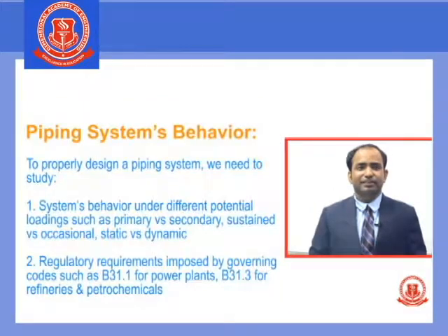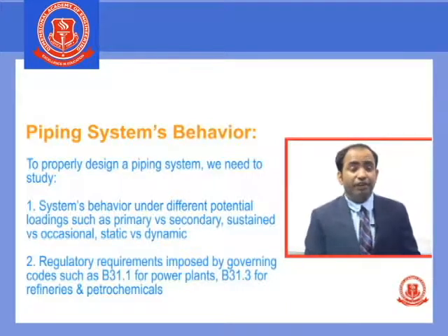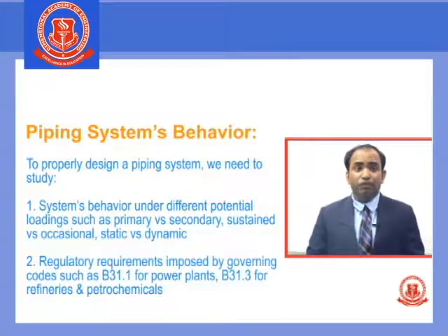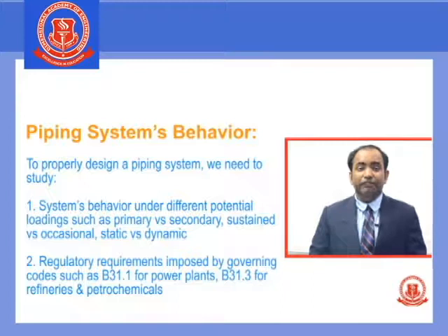To understand the piping system, we need to understand the behavior of the piping system. We need to do the behavior study under different potential loading conditions, such as primary versus secondary, sustained versus occasional, static versus dynamic. Under all the different possible potential loadings, the piping system behaves differently.